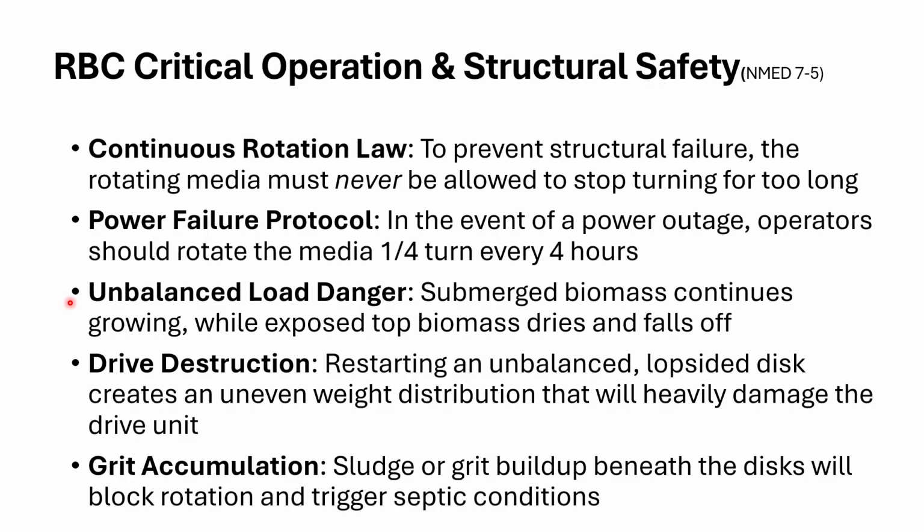You'll hear a rumbling if the load's unbalanced. Same thing here. It means basically we've got too much weight on one side of the RBC, and we're really going to cause ourselves bearing problems and load problems. But that submerged biomass is going to grow, and the top, because it's not getting any food and it's drying out, is going to die and slough off. It's going to fall off. So we're really going to have an unbalanced load here.